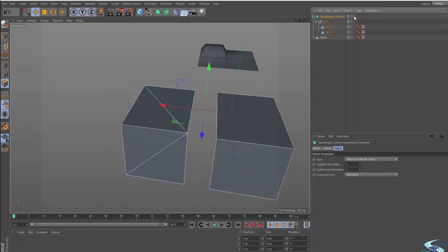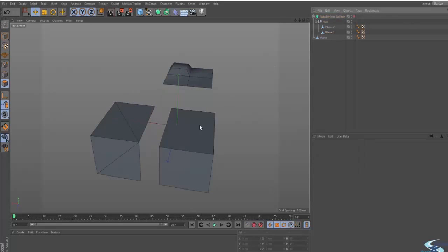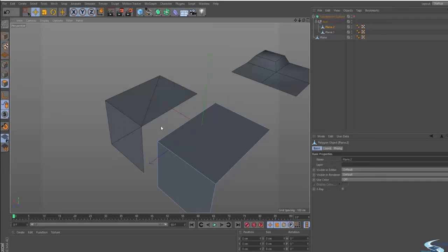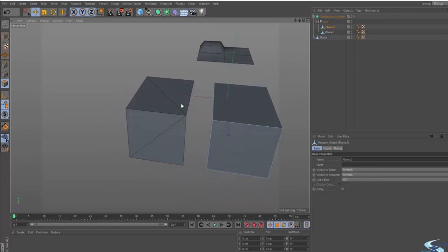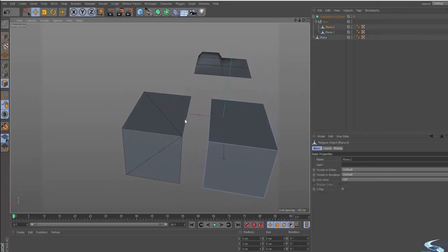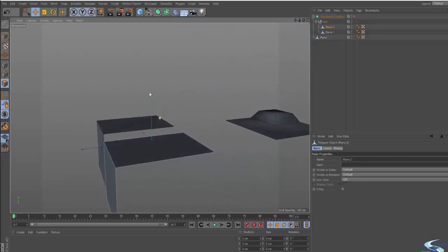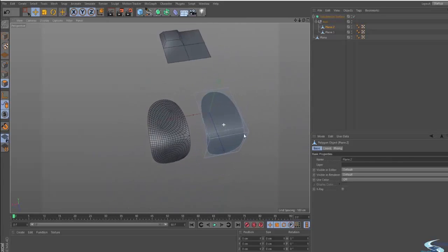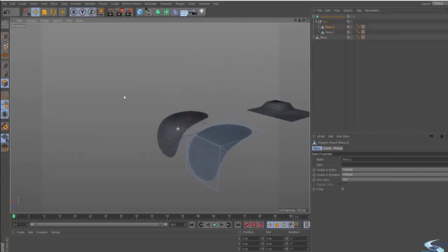And these subdivision surfaces, they want only quads. We only want to use quads. If we have a triangle, then we want to find some kind of a way that we can create cuts or change the geometry around to remove these triangles, because the triangles make the smoothing bad. As you could see right here, they don't smooth properly. They make this kind of stuff, and we don't want this in our models.